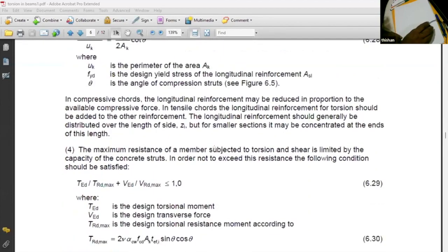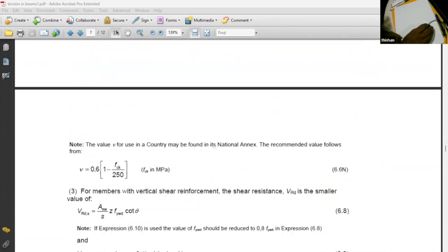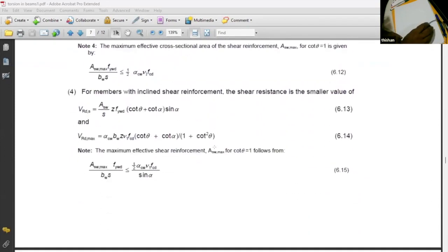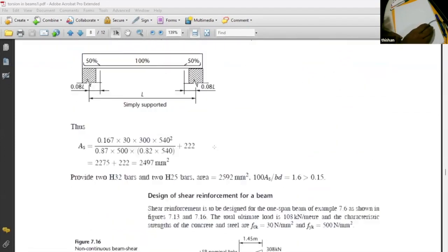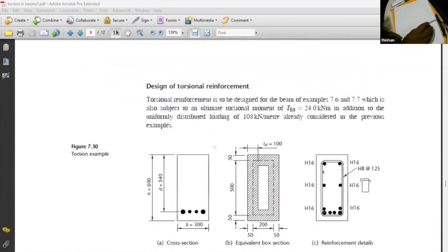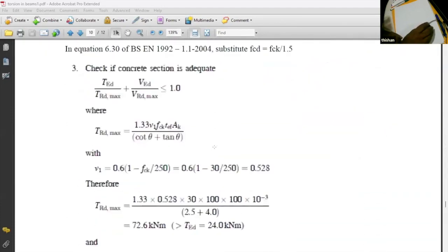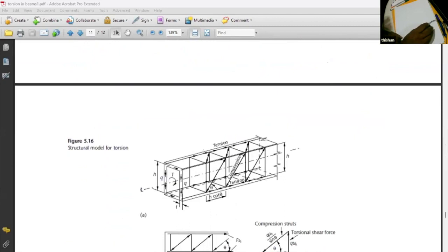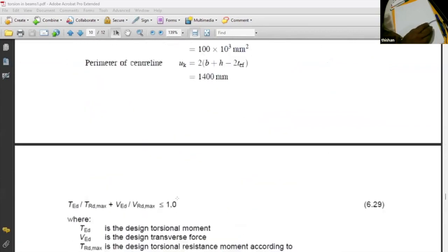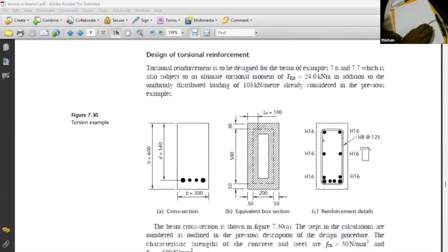If I try to use the diagram that is available in the notes, before I move on to the white sheet, here you are. This is how the torsional shear flows. Can you remember last time? We said when you are designing a rectangular section, we design it as a hollow section and then provide the reinforcement requirement, right? Yes, sir.